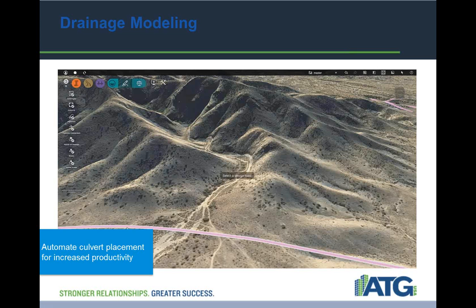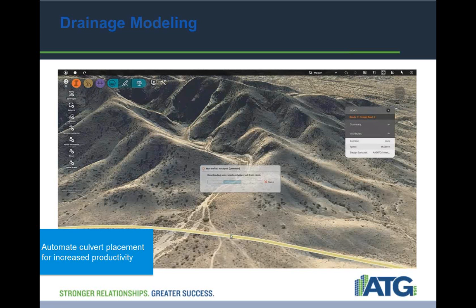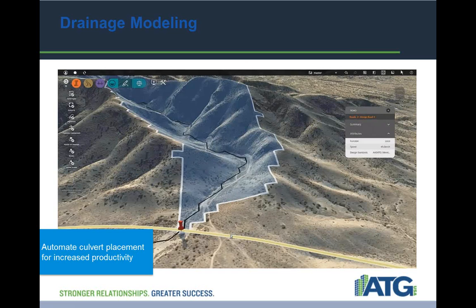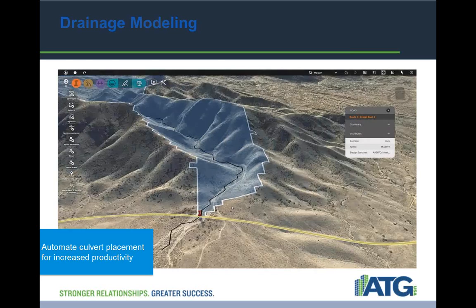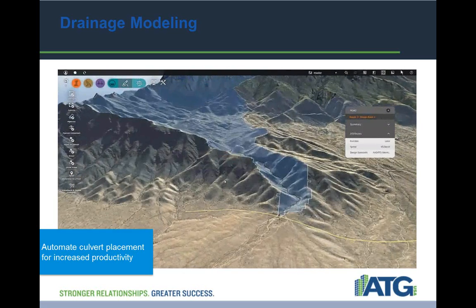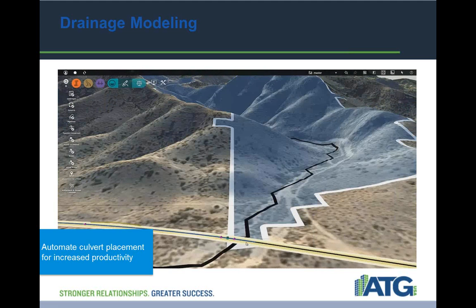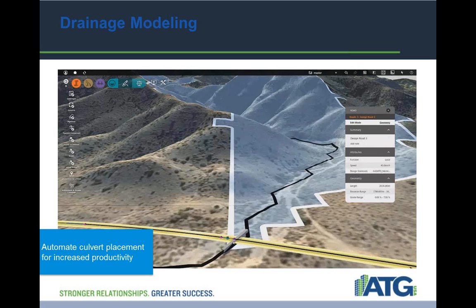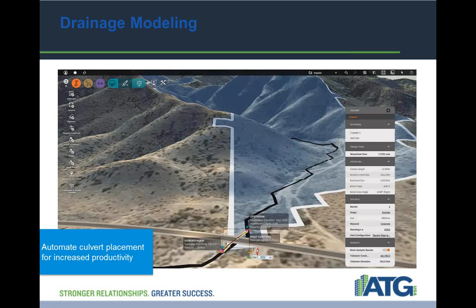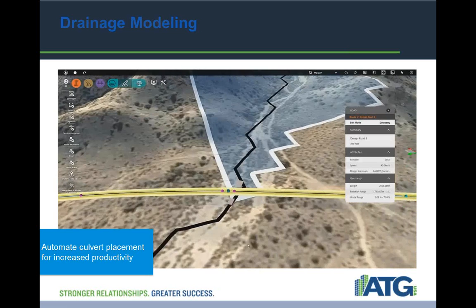Within the drainage modeling is an automated culvert placement at linear waterway crossings using the predetermined rules. The drainage modeling is associated with roadway layout, and locations are adjusted as the road changes. You can assign a USGS National Stream State Regression equation and parameters to compute the runoff from the defined watershed.